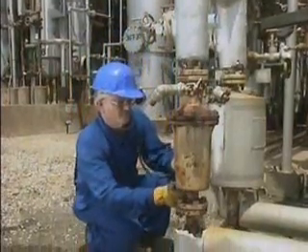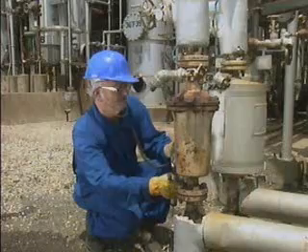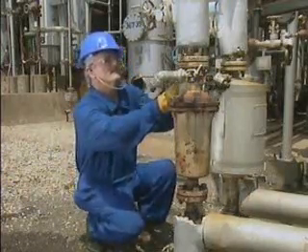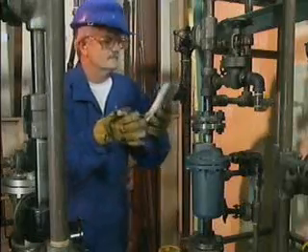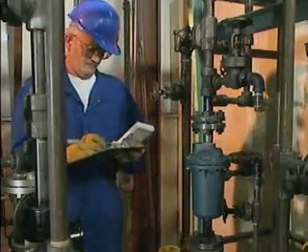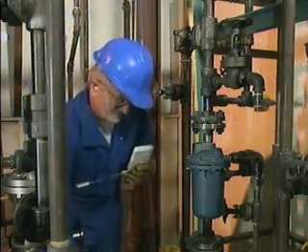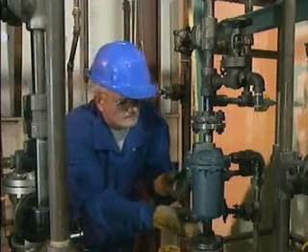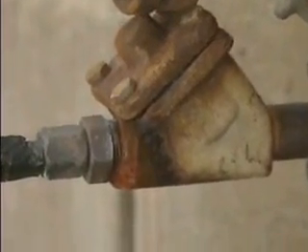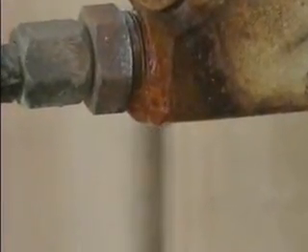Trap surveys should be performed on a regular basis. A trap's size, pressure, and workload will determine exactly how often a survey should be conducted. Keep a record of trap performance as an aid for determining if a trap has a high failure rate. A trap that fails several times within its normal service life should be investigated. The failures could be a sign that the trap was installed incorrectly, or that the wrong type of trap is being used for the application.